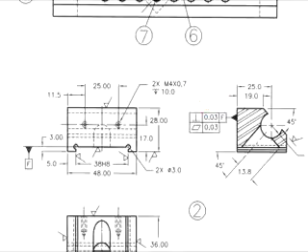Now, flatness isn't referred to F because flatness isn't a related geometric tolerance. In other words, if something is perpendicular, well, it has to be perpendicular to something else. But if something is flat, it cannot be flat to something else. Flatness is an ideal. And where is my reference surface F?